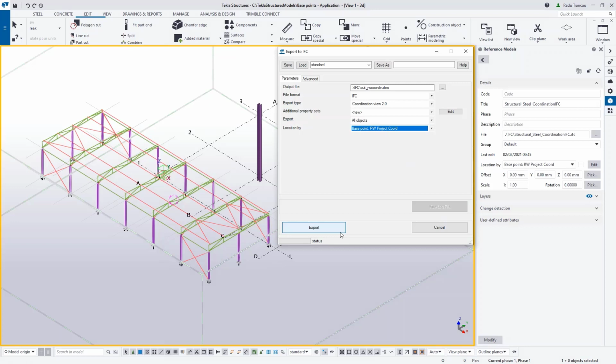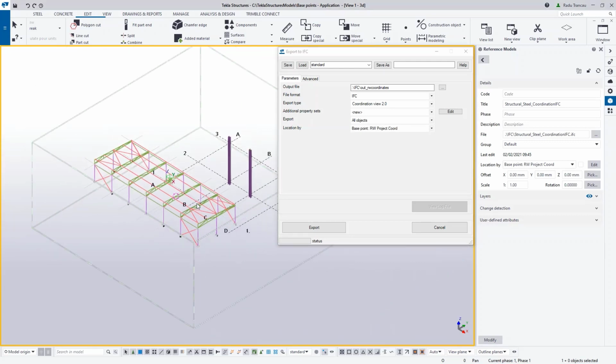Make sure whenever you're doing both the import and the export exercise to get a project coordination base point, which you may receive from somebody who's giving you the IFC, or as we've seen, you may deduce either from the IFC file straight away using that class for Tekla exports, or just by going back and forth and trying to guess your coordinates.